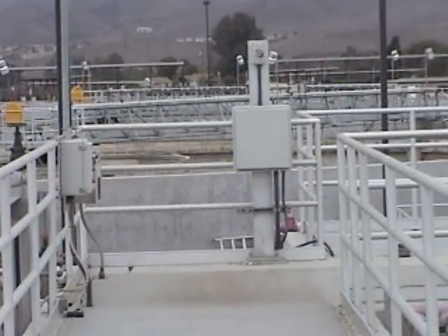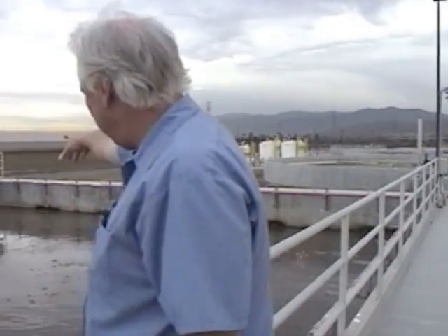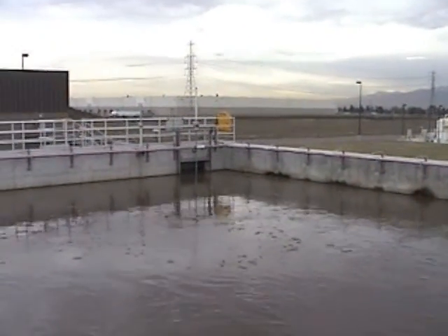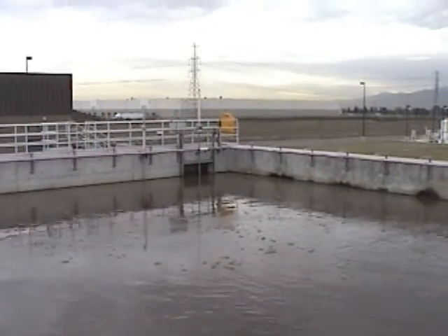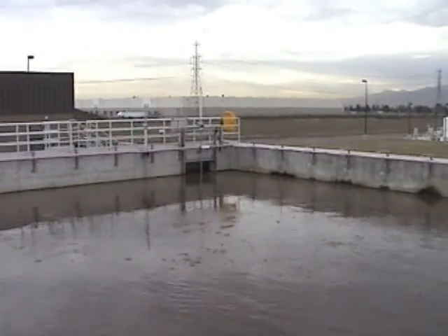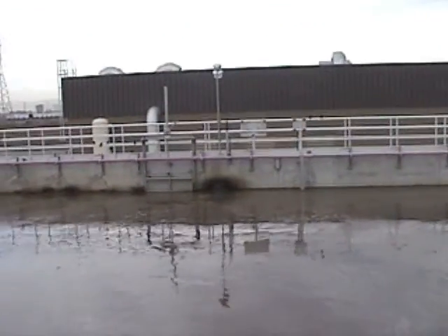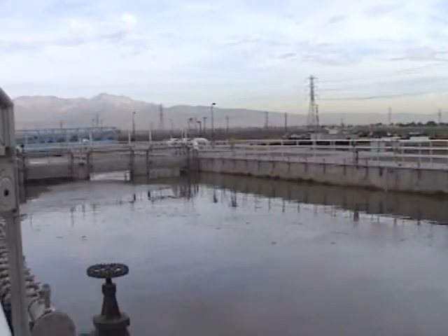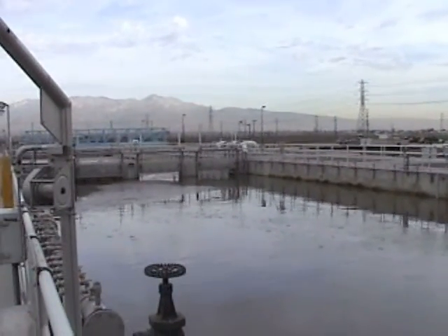The gates here, that's primary effluent. Right now we found the most efficient way to treat our flows is by having this gate on the very end all the way open. But if you wanted to, you can do what they call step feed and have primary effluent enter through that gate over there. There's several gates along this train that you can open up and vary the characteristics of the inflow.